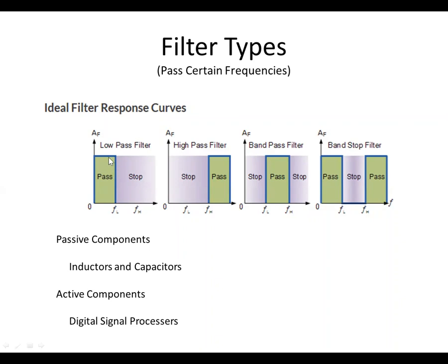But the fact of the matter is that with a low pass filter, this drop is typically around the knee, and it comes down and never really does eliminate 100% of the higher frequencies. There are ways of making this drop-off rate sharper, so you do a better job of eliminating the higher frequencies. The higher Q filters have sharper drop-offs and do a better job of eliminating the higher frequencies, at the cost of a more complex circuit and usually more expense.